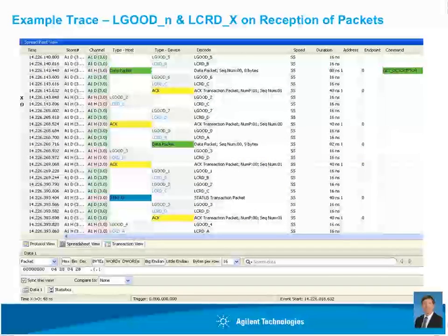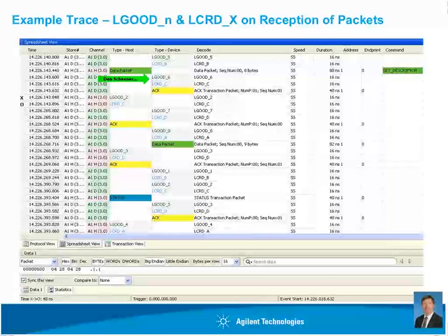Here's a data packet. A data packet goes across the link. It's a GET descriptor. At the higher levels, so remember our different sequences, there's the data transaction, and the transaction comes back with an acknowledgement here, but the link level is still doing its acknowledgments of receiving that packet. So there's this whole timing sequence of it has to process it through the buffer first before it sends the acknowledgement back from the other end. And that information flowing back and forth across that link, and being able to see all that information.